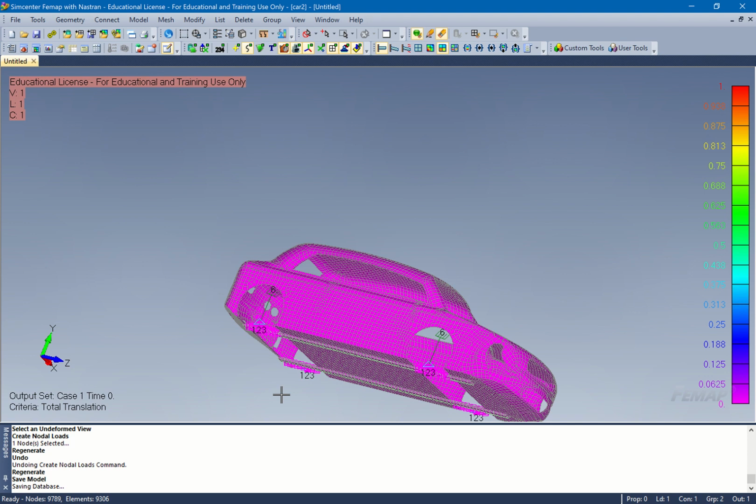So you only need 3 properties for the springs and 1 property for the damper. Does that make sense? And definitely, even though the load's on the one side, do the spring on the other side also. Then you can actually see the car walk on the suspension.